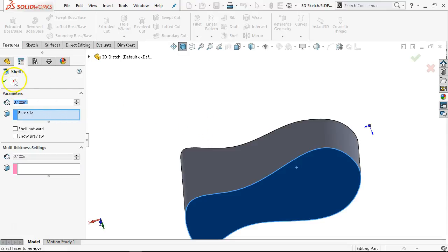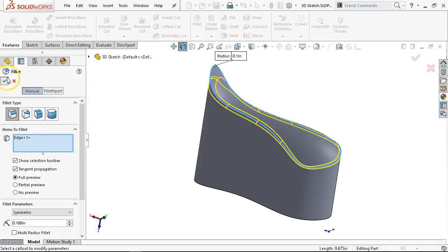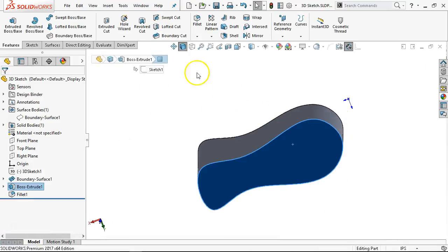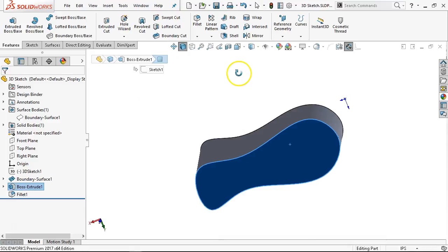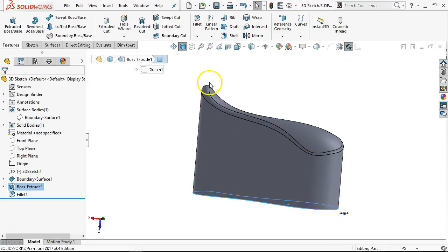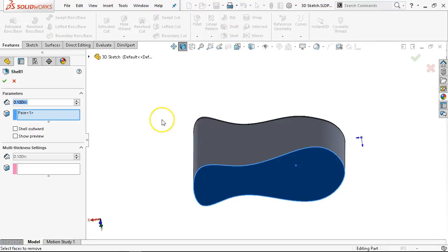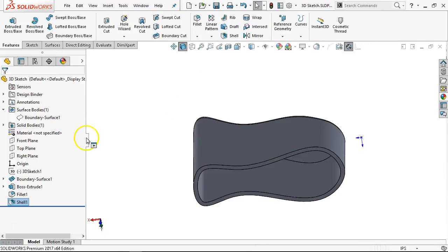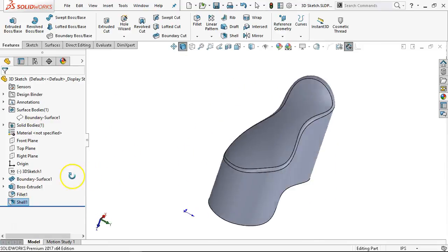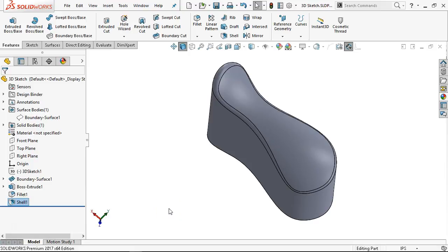And see what it gives for, well, actually, before I shell it, let's put a little bit of a fillet on. That will help it with the transition. And unless I want to do a lot of EDM electrode making, having that very sharp, not a good idea. All right, so we'll see what it looks like with 100 thousandths wall. All right, so the inside, the outside. My next mouse project, operate it this way.